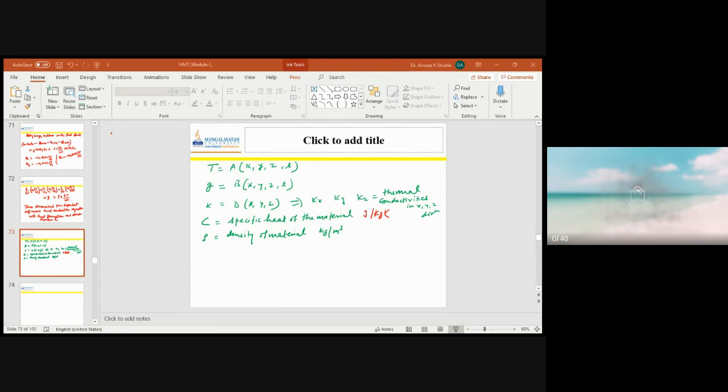material or element. So what is the meaning of isotropic material? It's a kind of material in which thermal conductivity is constant in all directions, it doesn't vary. So for isotropic material, for case 1, kx equals ky equals kz, and we can simply take it as k.